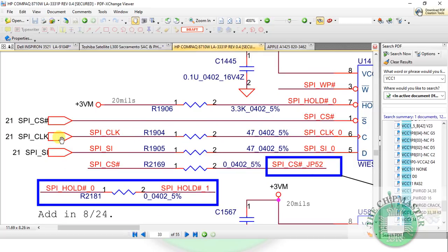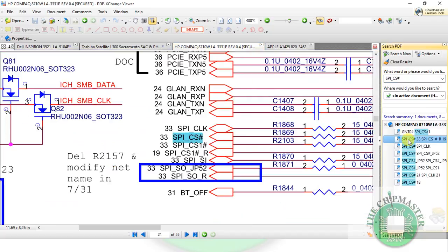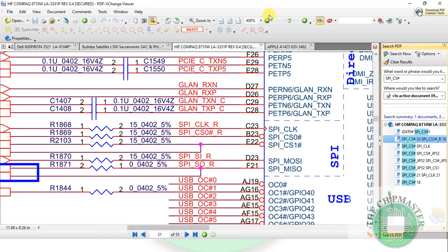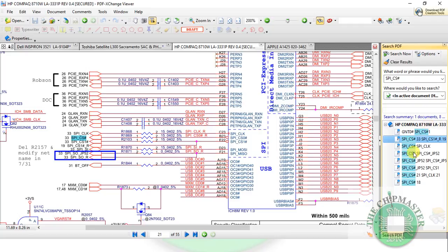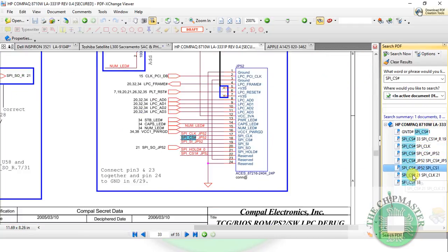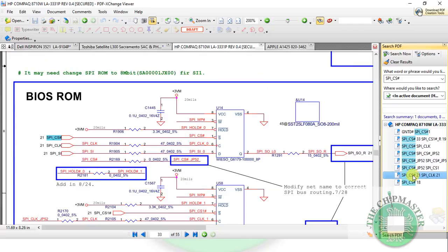As you can see, SPI chip select, which is the main selection. This is the signal that the EC, or the ICH, will use to select the chip to read. Alright, so let's go to this section. This is the South bridge. That's going. This is our test point.